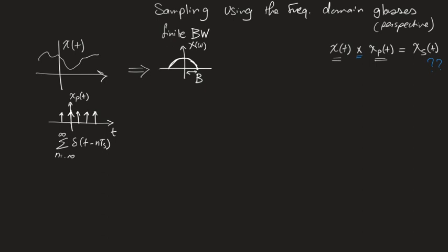Anyways, keeping that in mind, this is a famous time domain signal that has its Fourier transform represented in the table of Fourier transforms. So you don't even need to calculate the Fourier transform of this, relying on the fact that it is periodic. You just need to look at the table, and you will find that the Fourier transform of this train of deltas in time domain is, interestingly, also a train of deltas in frequency domain. So versus omega, we still have a train of deltas, okay?